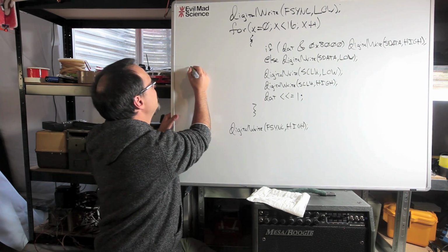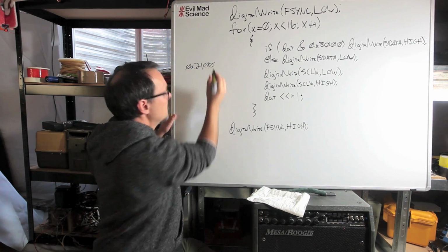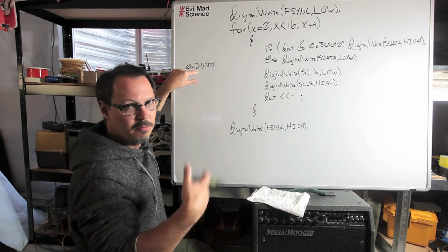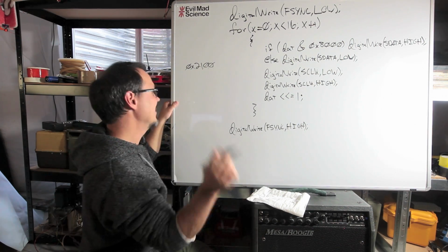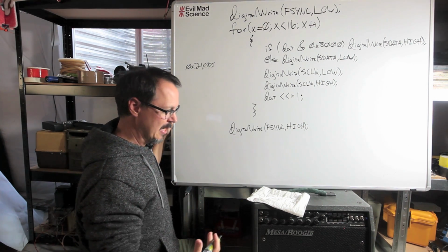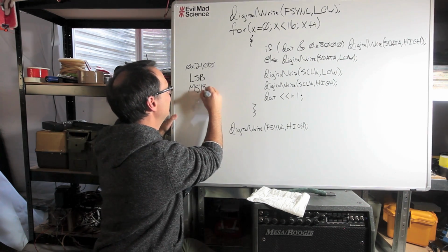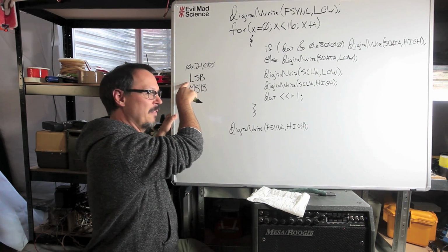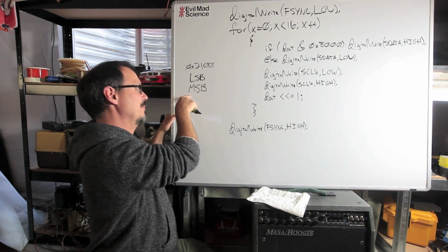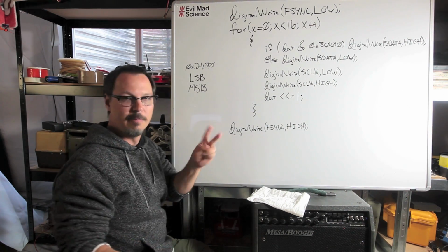The first one you have to send, and I'm going to say hex values, 0x2100. This command basically shuts the thing off and gets it ready to change its parameters. Then it sends, and this is a little confusing, there's 28 bits. It sends the lower 14 bits, LSB, and then MSB, but the trick is it's not sending bit 0 first, it's sending bit 13 first, and then it scrolls through to bit 0, and then it sends bit 28 or something, and it's still a 16-bit transfer, but the upper 2 bits are 0.